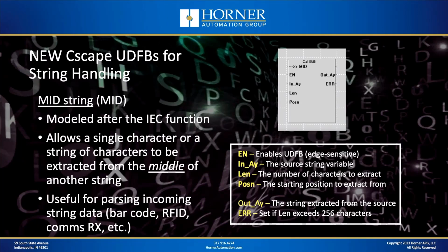So you're going to have a source string, and then there's one or more characters that you want to extract from that and store as a separate string. It's very useful for doing things like parsing incoming data from a barcode reader or an RFID type tag or something like that. So let's talk about the inputs and the outputs for this user-defined function block.